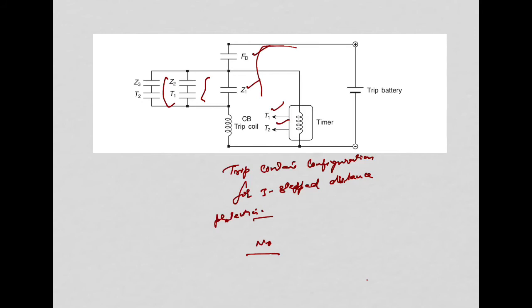Now, the three-step protection for a three-phase line against all the 10 faults. We have already seen that three phase fault measuring units, which are fed with the delta voltage and delta currents, and three ground fault measuring units, which are fed with the phase voltage and phase current compensated with the residual current, are required for the complete protection of the three-phase line against all the ten faults.